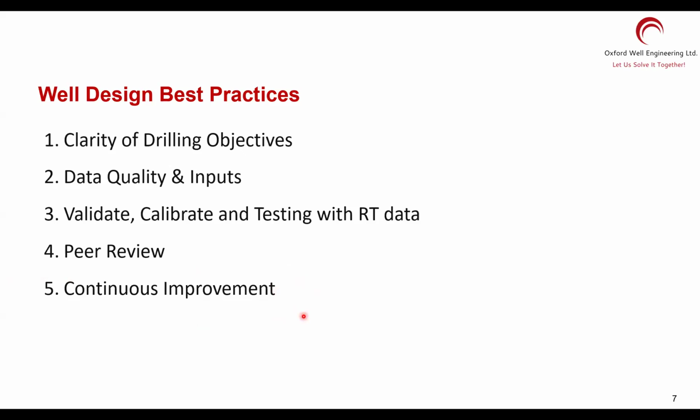And that's something that actually materialized in one of my projects. We were using MPD every time. At one time, because I was new to that area, I asked that question: why are we using MPD continuously? It costs 10% of the well cost. The gentleman said, if you don't like it, why don't you find out? So I drew all the data and plotted everything, and we found out that they actually did not need MPD. There was a drilling window, and we did a study on it.